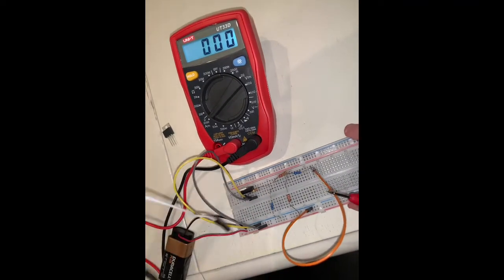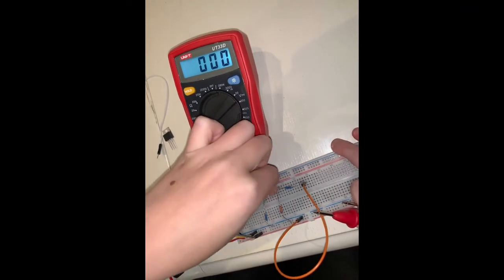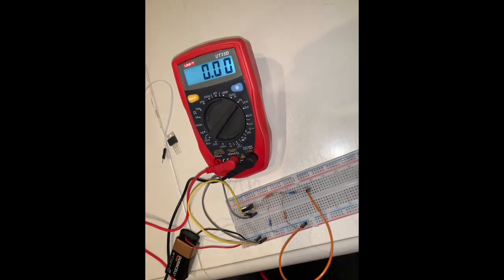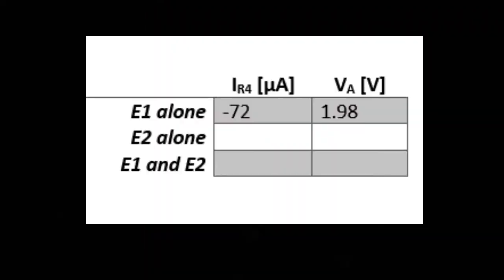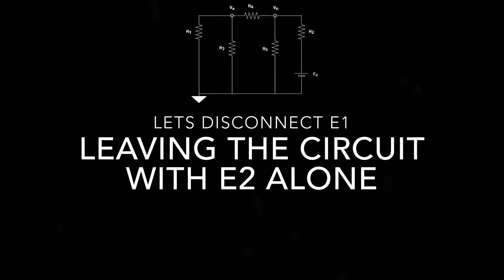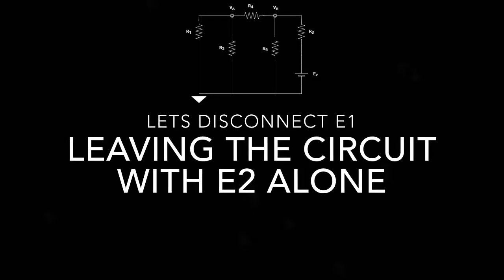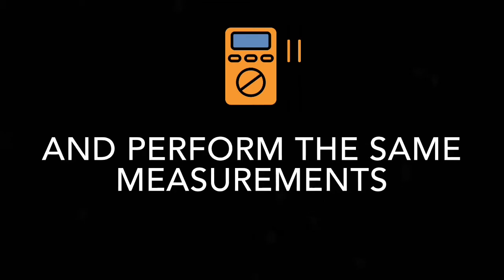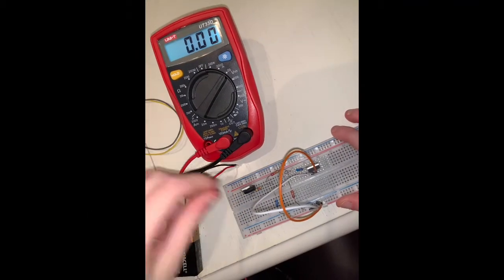Remember to put the resistor back in place before measuring the voltage at node A. When measuring the voltage, I'm measuring from the node to the ground and get 1.98 volts. Let's insert these measurements in a table. After putting E2 back in place, we short circuit E1 the same way as before and perform the same measurements. Don't forget in what direction you are measuring.